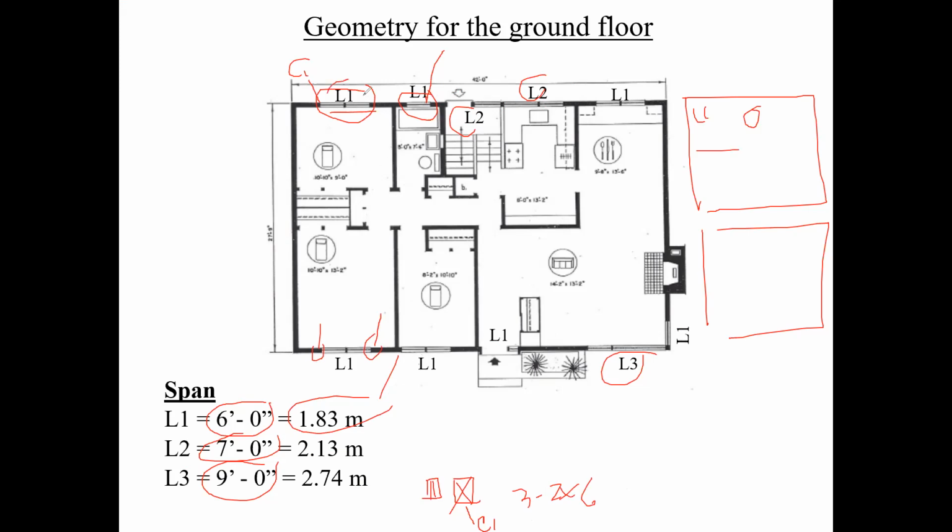And the same thing here, you can actually put L1, L1, L2, L2, and then you can have a legend here saying L1 is 3 by 8 by whatever, you understand? And you can have a schedule showing what these lintels are, or you can actually put them right on the drawing. It's up to you. So that's for the lintels. Does anybody have any questions?